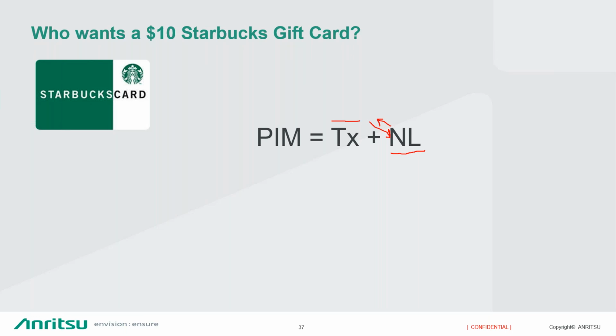What is the ratio of the optical splitter, 10/90? Yeah, we're using 70/30. That has worked with 100% of the network equipment that we've gone to today.